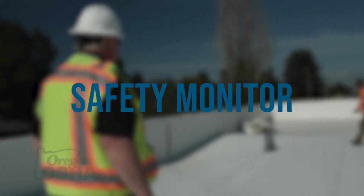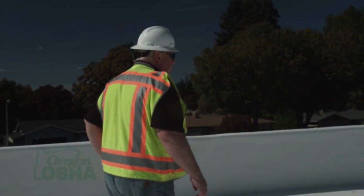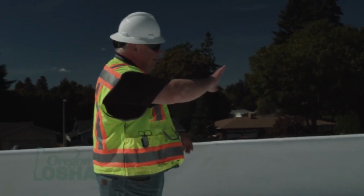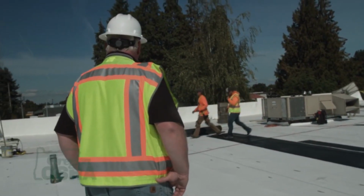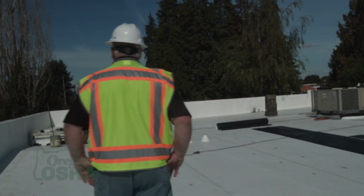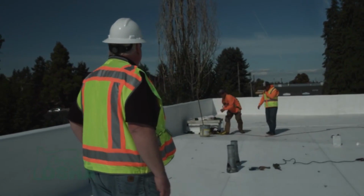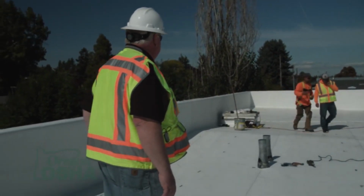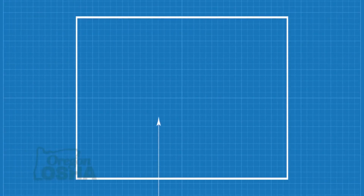Next is safety monitor systems. The safety monitor system uses a competent person to warn roofers when they are in danger of falling. Since the safety monitor is responsible for recognizing fall hazards and warning workers about them, they are required to stay on the same walking working surface as the roofers and avoid doing any other work. The safety monitor system is available as a primary fall protection option for roofs that are 50 feet or less in width.